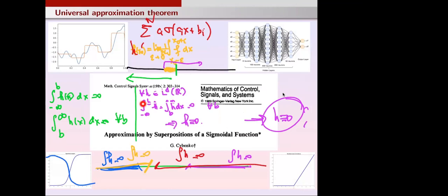I don't know whether you ever did the experience of computing in MATLAB: you take the PDE solver and you solve the Laplace equation in 1D, and then you see a parabola. The exact solution is the parabola, a very nice quadratic function. You do it with finite differences or finite elements. Of course, you know that the solution given by finite elements is piecewise linear, not a nice smooth quadratic parabola. But as soon as you put a large number of elements, to the human eye you will not be able to see the gap between the parabola and the piecewise linear approximation.